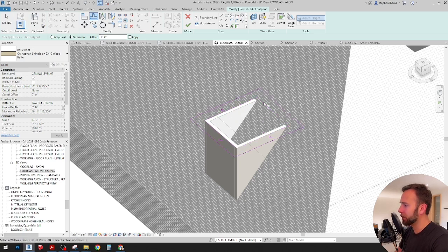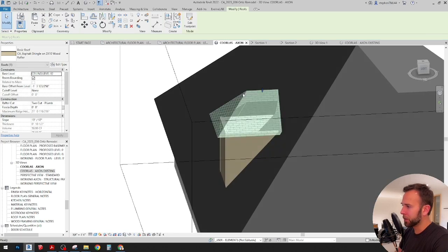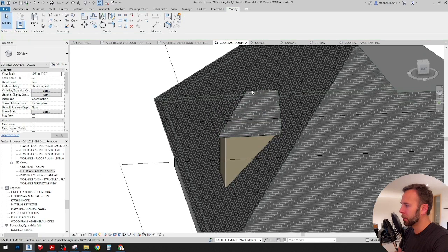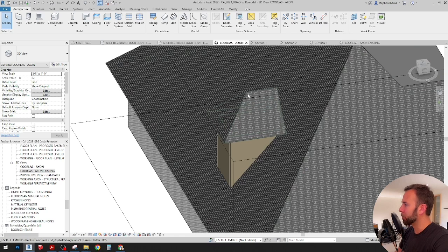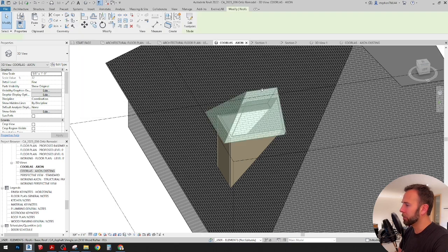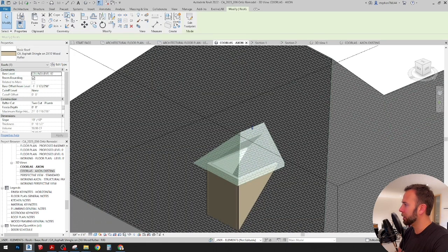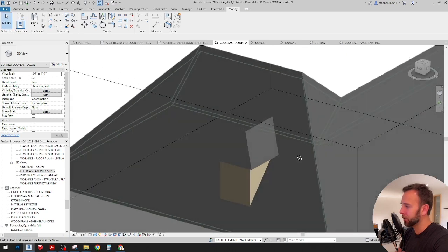Don't copy, offset. Bring that one back. And let's see what it comes up with there. So the dormer tool, there's a cutout dormer tool, and then there's actually a snap dormer tool, and the modify, this little guy up here, join, unjoin roof. So I think if we select this and then this, or you select the button, then the edge of that, and then snap it to that roof, and it kind of pulls it back there like that for you.